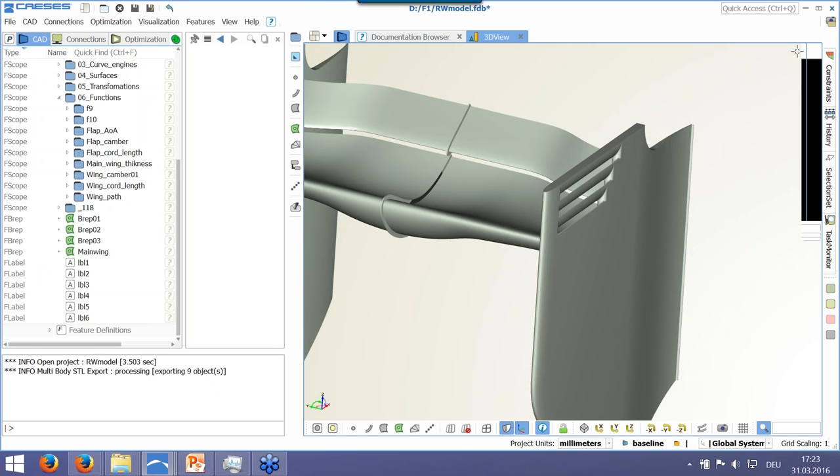The idea why we don't need vortices, so why the vortices are not good, is because they create an induced drag. The idea behind induced drag is that this flow will create a downwash, and this downwash is like a vector of velocity.